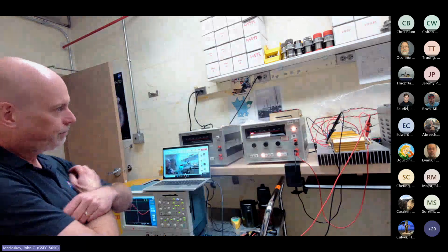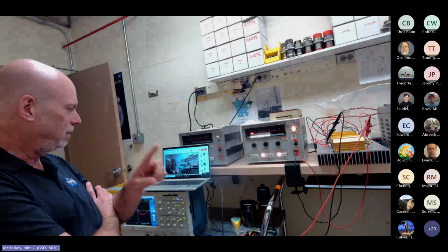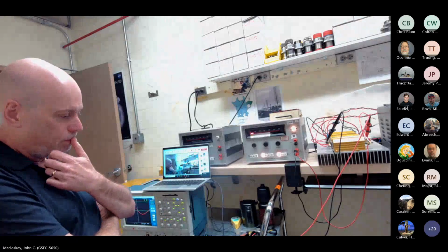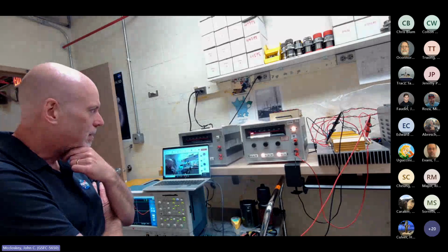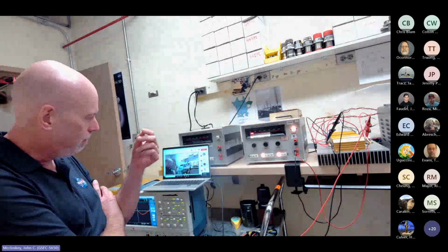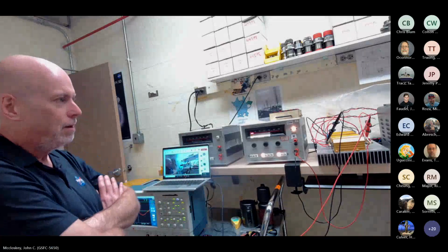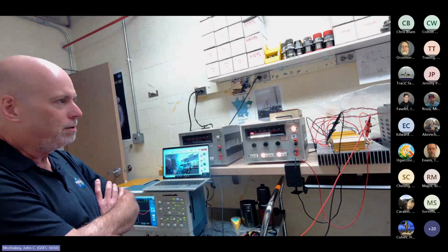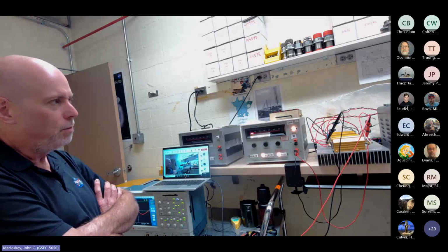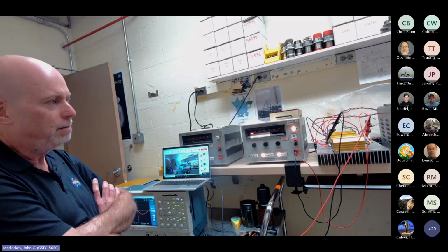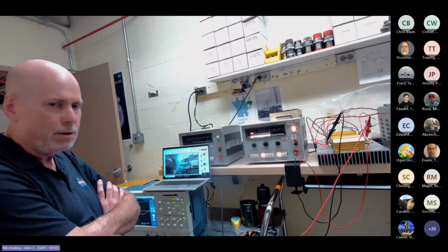Yeah, I mean, a lot of people have expressed concerns. The negative going transient doesn't really seem to pose any real damage concern, right? You're pulling the bus voltage down to 0 and then it recovers, and if it causes your equipment to be disrupted, generally the worst case is, well, okay, it's disrupted, but it recovers and you get on with life, right?